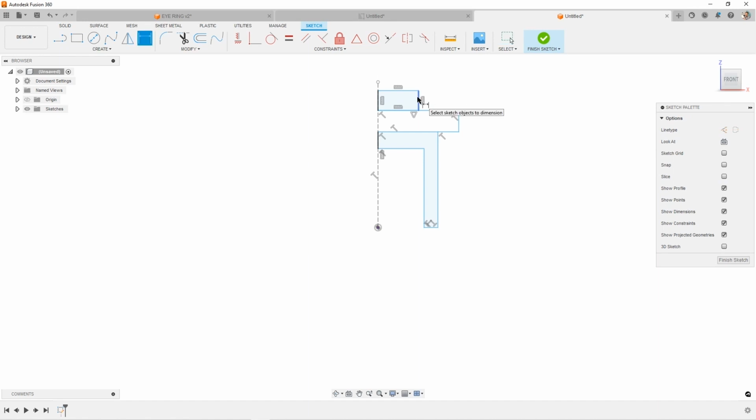Now let's drop in some dimensions. So here's the important thing. I have this construction line, and I know all of these values, or I know some of them, as diameters, as in it's the double dimension when we're doing a revolve. So when I come over and place this, you'll notice that it's just half of a total revolve. That's not how I want to do it. Instead, I'm going to dimension from the construction line to this line. And then before I place it, I'll right click and do diameter. That lets me place the doubled version, or the diameter version, of what I want.